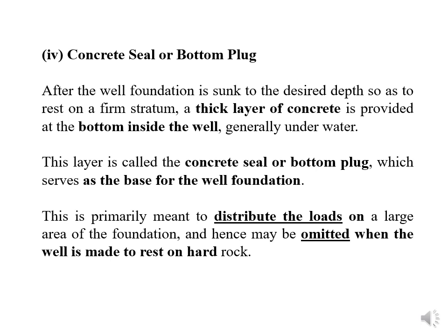The concrete plug distributes the loads on a large area of the foundation, hence it may be omitted when the well is made to rest on hard rock. See, omitted, it is highlighted and underlined here. Omitted means if you are going to sink the well in the river up to the hard strata, concrete sealing is not required, right? If hard strata is not there, in that case you have to go for the concrete seal or bottom plug.